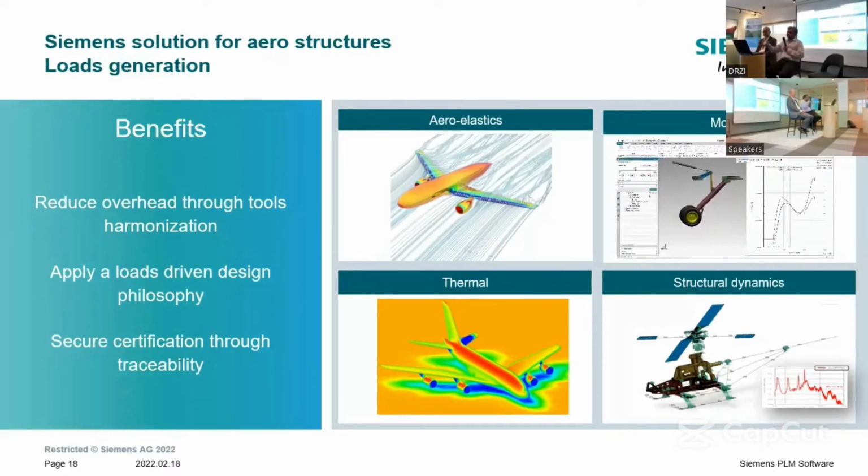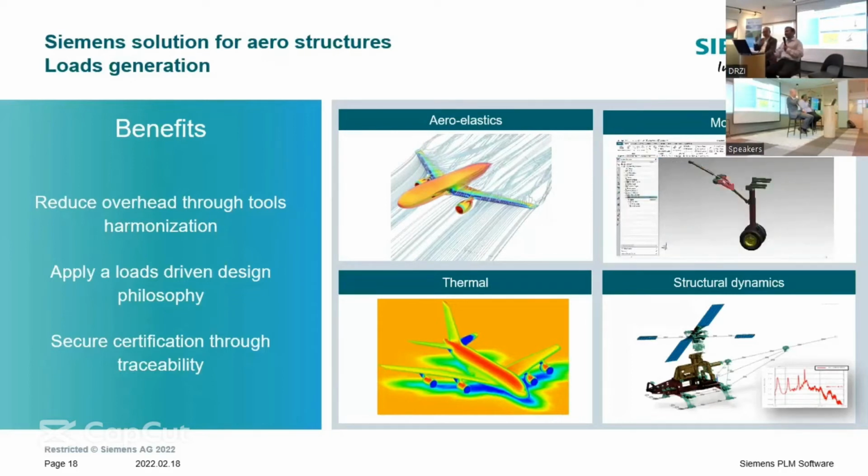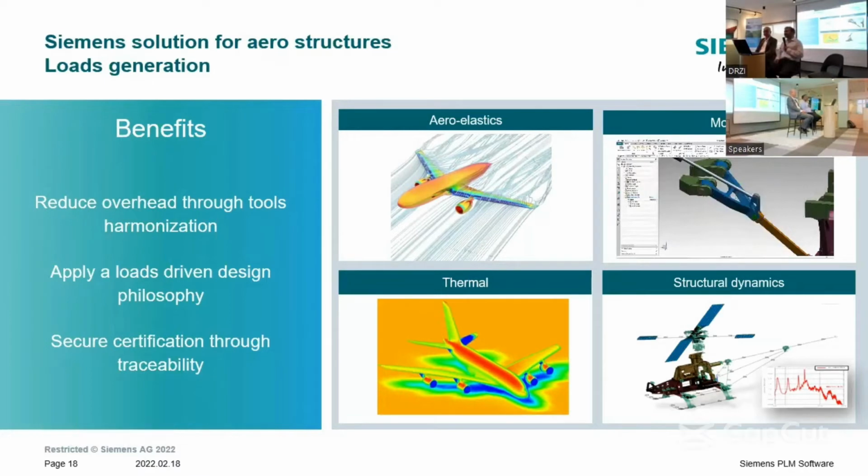So here is where we are applying multi-physics. If your drone is going to get the load because of the fluid or air environment, we can simulate the airflow and we can simulate the load acting on the structures. But at the same time, if certain components or mechanisms are supposed to carry certain load, or if there is some mechanism to pick and place, you may also have physics to calculate the loads acting on the structures. And not only that, for drones that fly in the air, there is also another phenomenon, flutter.